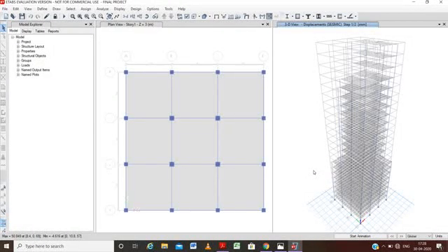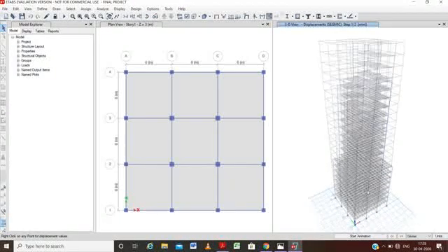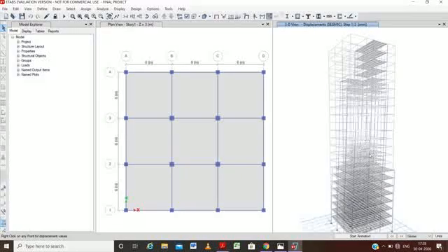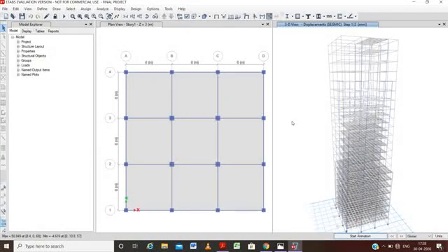And here in the 3D tab we can watch all the spectrum for this, and we just have to rotate it to get a view of the building response, how it has responded to the response spectrum and the seismic load. Here it is done. We can also start the animation at any time.